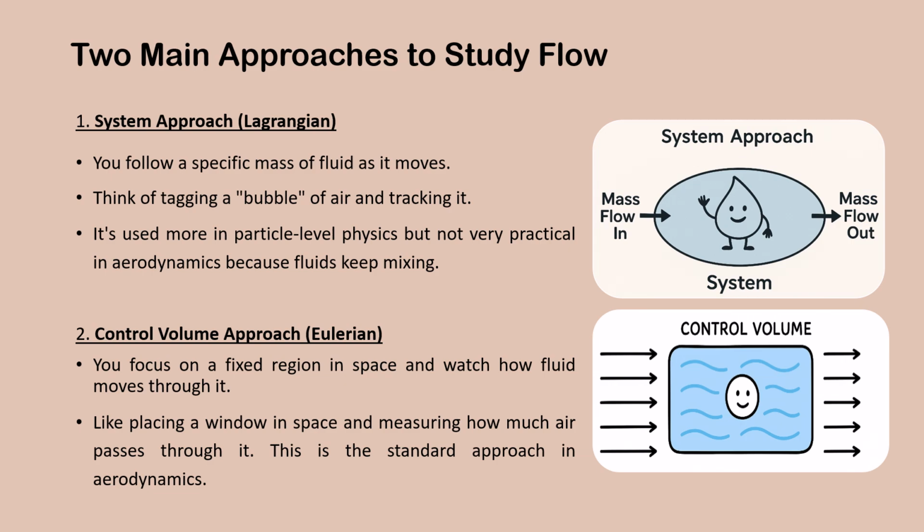The second is the control volume approach or Eulerian approach. Here we focus on a fixed region in space and study how fluid passes through it. It's like putting a window in space and observing how air moves in and out. This is the standard method used in aerodynamics.